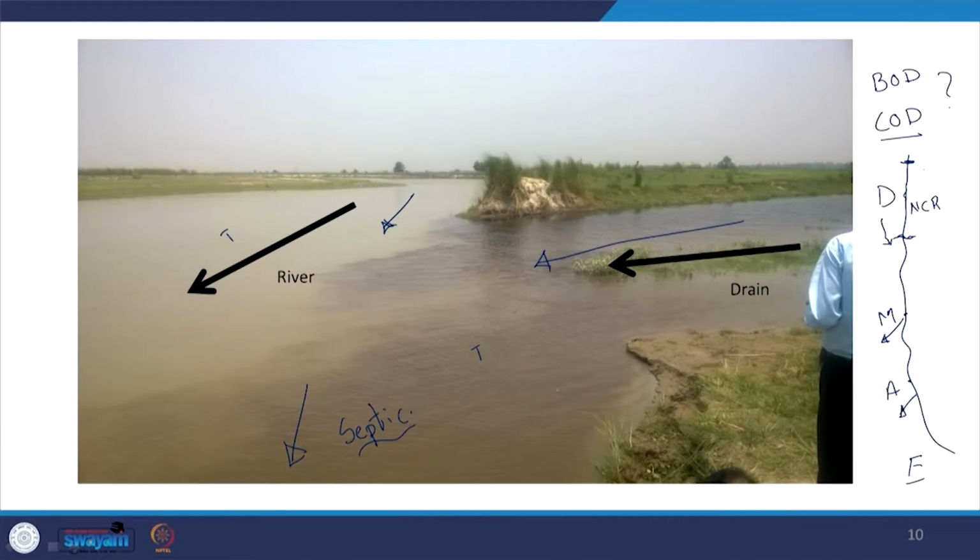Again, whatever we discharge ends up being consumed by us. Let us say here we have the agricultural fields and this wastewater is used out here. Let us say we have these persistent organics, which I am right now calling emerging contaminants, more of this later. For example, a pharmaceutical compound or an antibiotic I have taken, only some of it, let us say 20-25%, will be used or consumed by my body, and the rest is going to be flushed out through the system, urine or feces, and it is going to reach the wastewater.